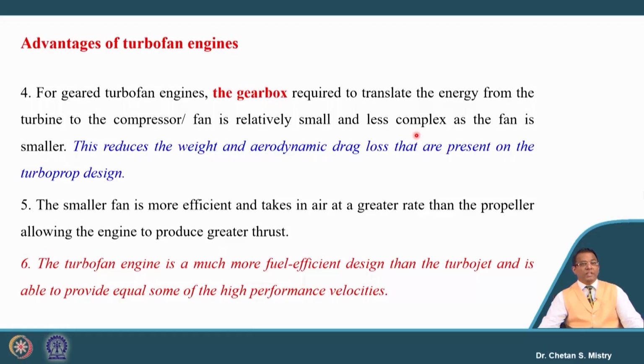Same way for the geared turbofan engine, we will be discussing this in detail. We have one dedicated week for the geared turbofan engine. In that case, the gearbox is used to rotate the fan, which rotates at low speed and has smaller dimensions, so it will not give the penalty in terms of weight as well as drag. That is what is a problem with our turboprop engine.